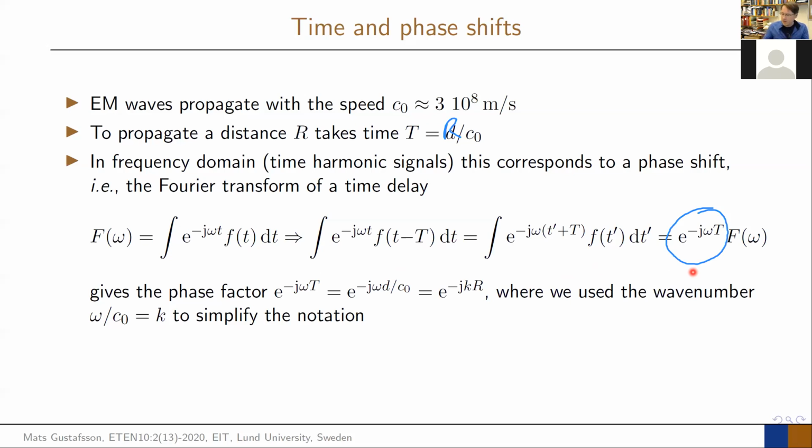So if I have an antenna where my receiver physically is closer to this point than this point, for example, the receiver is up here, I'm closer to this one and this one, then it takes shorter time to go from there to there than here to here. I need to compensate for that time shift. And I do that compensation by taking care of the phase that comes in.